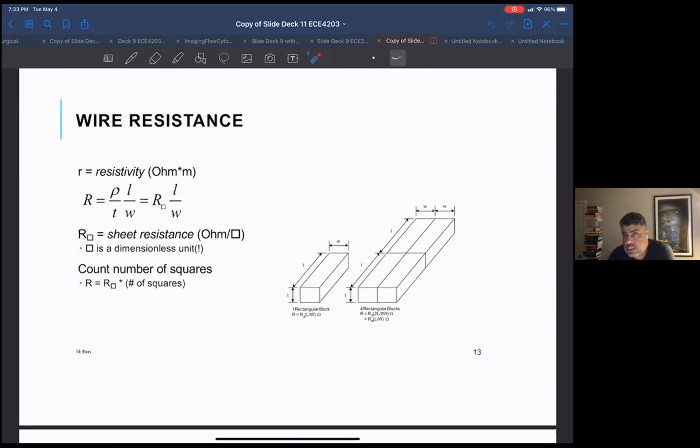Why is that? Well, the reason is almost every logic device, any digital device, is going to use minimum length devices. So they just take it as granted that your L is whatever's the minimum in this process, and you're just going to change the width. So they're not going to talk about capacitance per micron squared, which is really the appropriate thing to say.